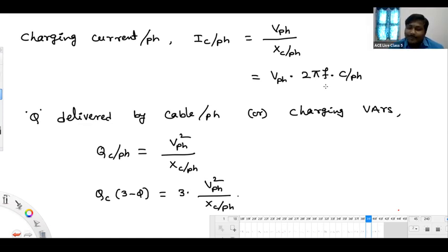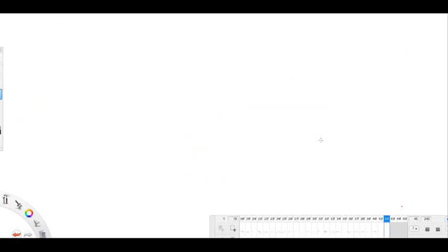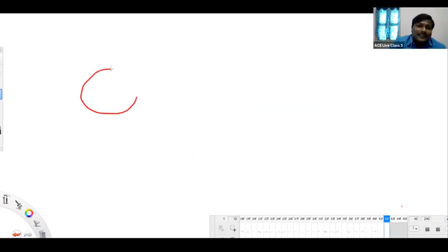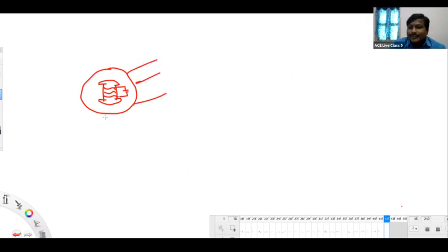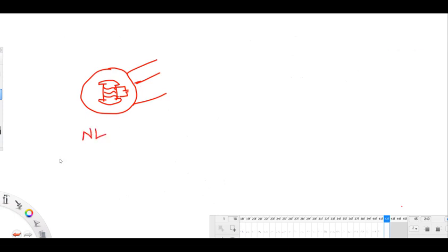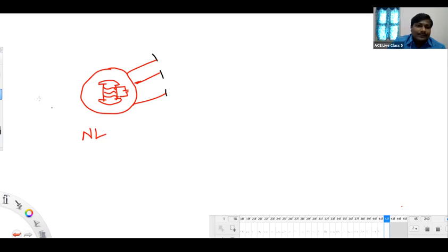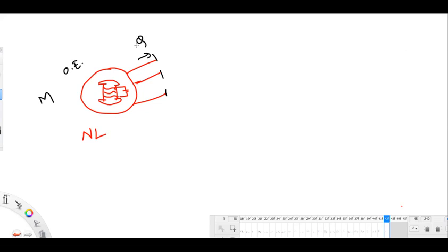Have you understood the synchronous motor clearly? If it is a synchronous motor, in the rotor body, I am showing the field winding, and we have a DC source here. And this is the three-phase supply coming, operating under no load. It is a bus bar. You say it's an over-excitation condition. Is it supplying reactive power into the bus? How is it supplying?